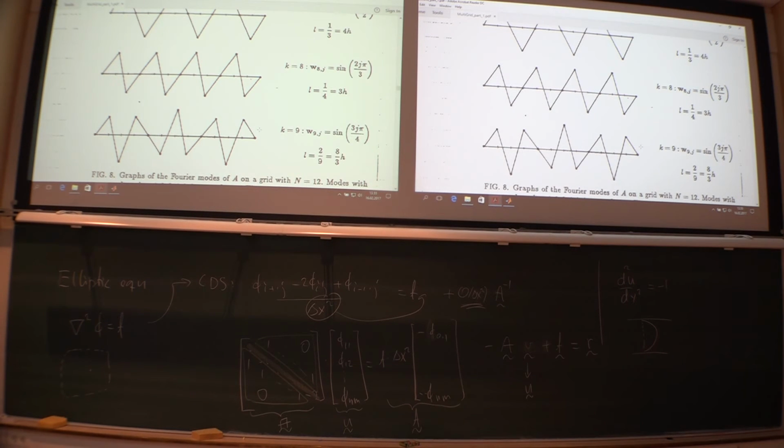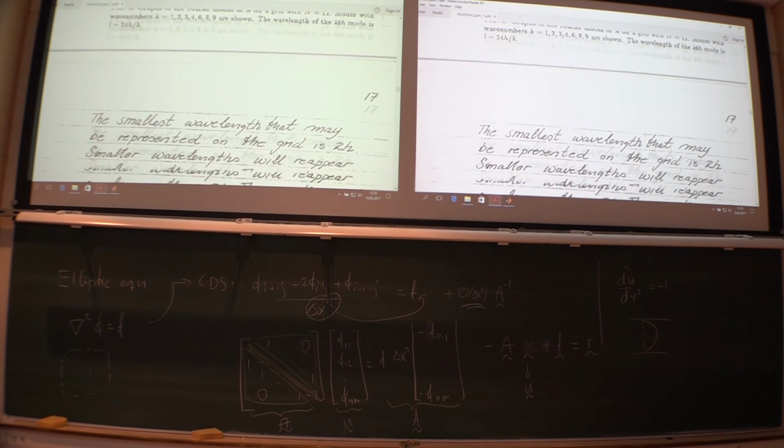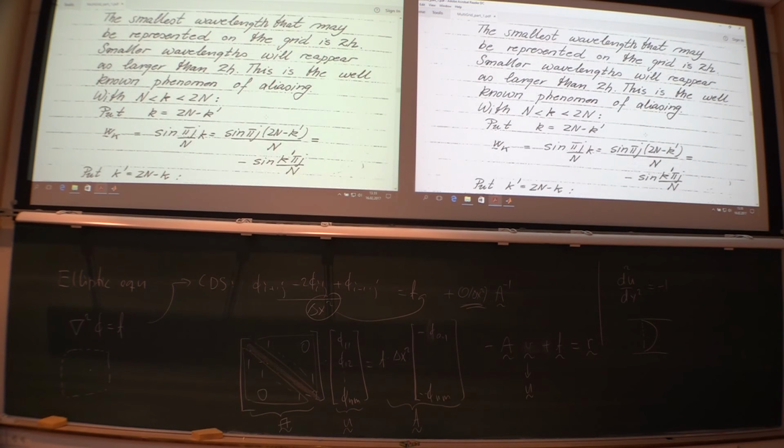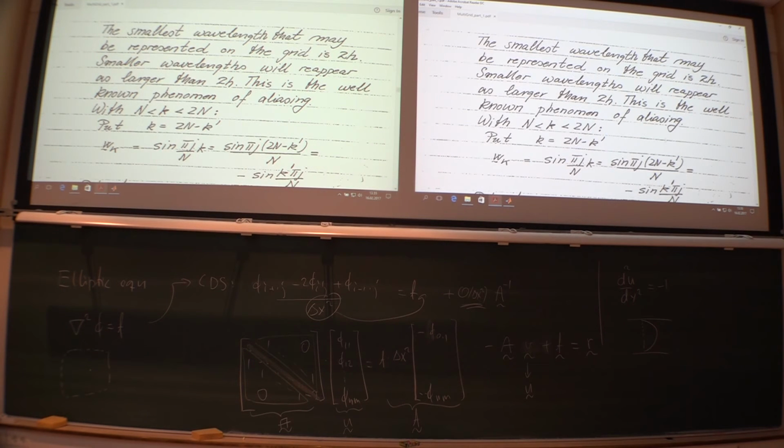You will have no system in it because we don't have enough points to describe it. So yes, it is definitely limited, depending on the number of points, how high a frequency you can represent. So don't overdo it here, definitely. The smallest wavelength will then be 2 times your delta x, and even smaller than that makes no sense.